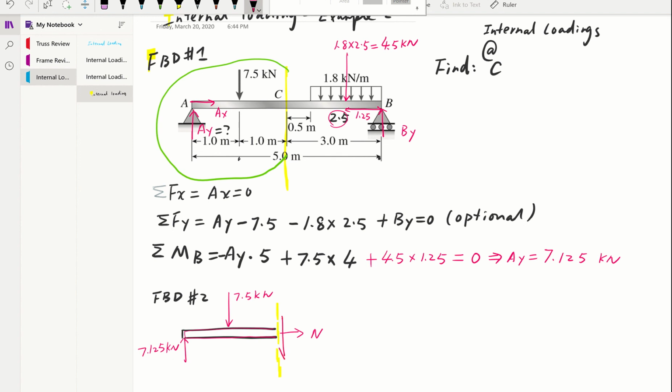So in order to do that, shear have to be parallel to the surface. So it's going to be up and down, and here to make it clockwise, it's going to go down, so that's V. Also, bending moment, we're going to make this beam bend like a happy smile. So in order to do that, that's going to be bending like this. So that's our 3 unknowns.